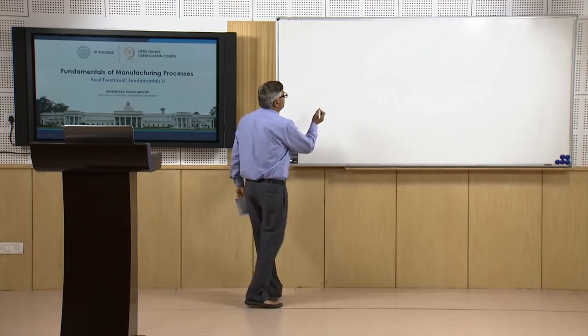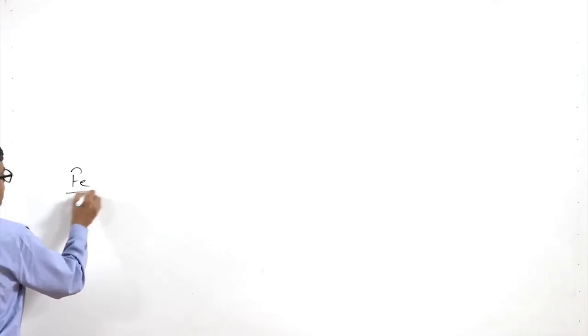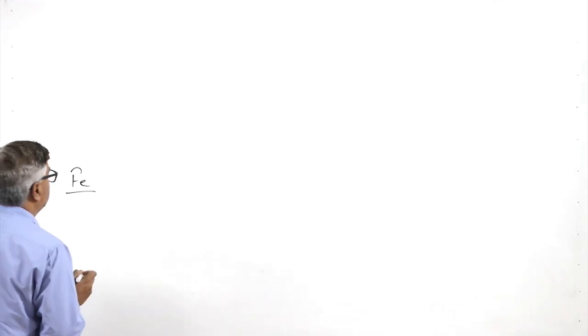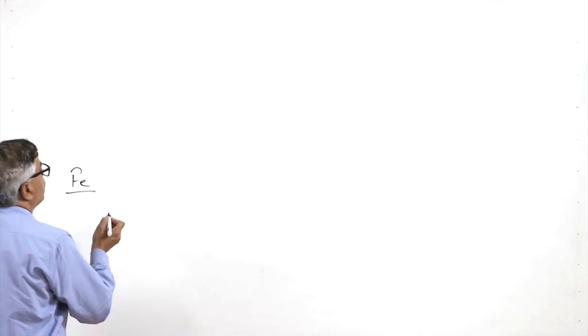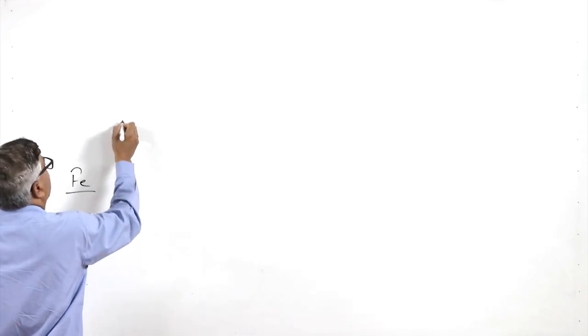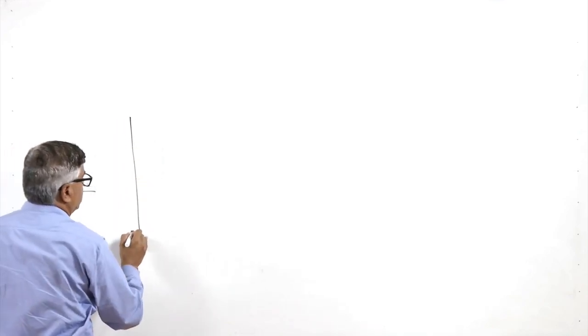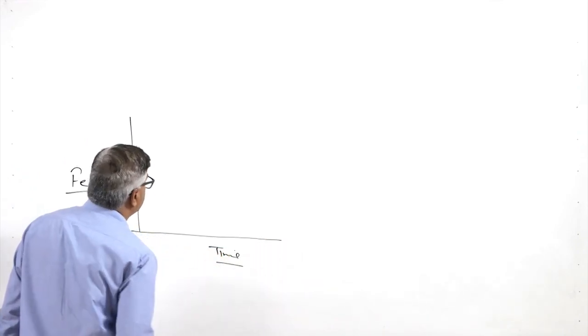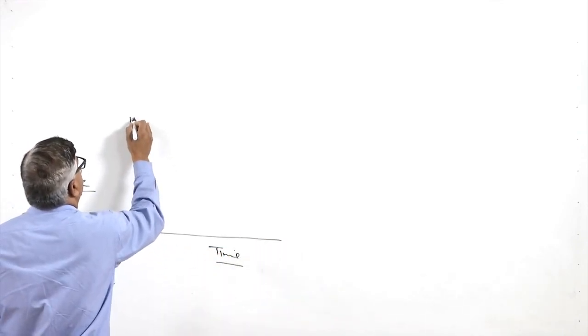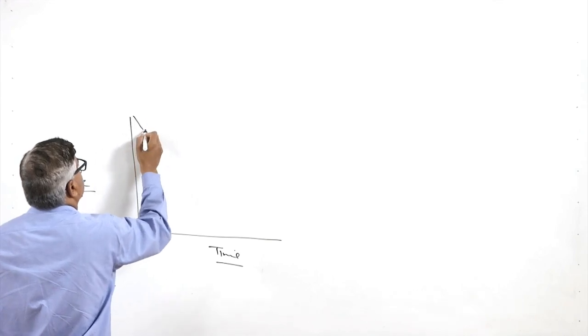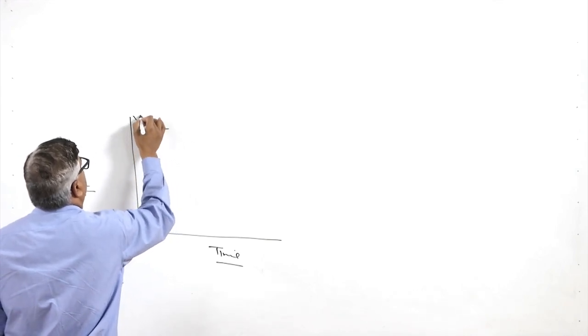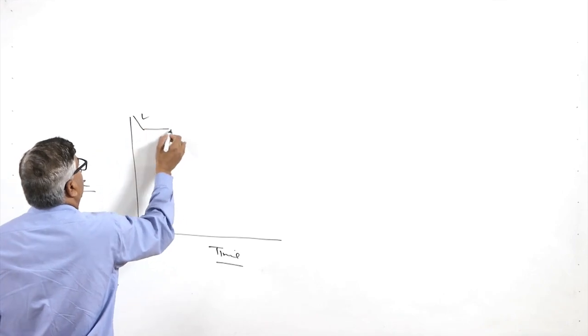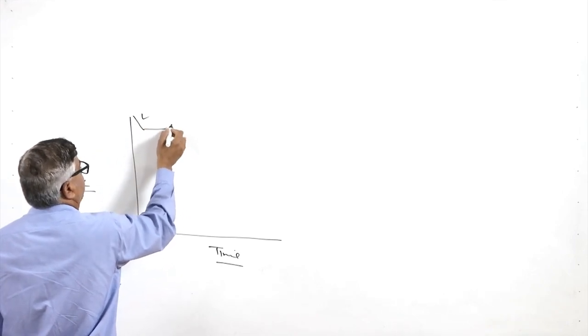So if we see, steel is an alloy of iron and carbon, which forms an interstitial solid solution. But iron in its pure form, when it is cooled from the molten state to room temperature gradually, as a function of time, the curve we get becomes like this. This is the constant temperature, above this it is liquid, and this is where it will be solidifying.